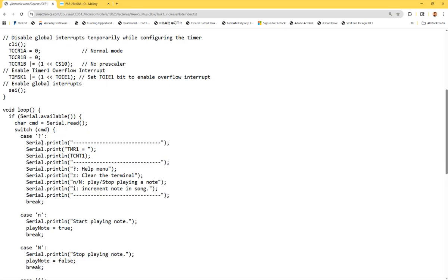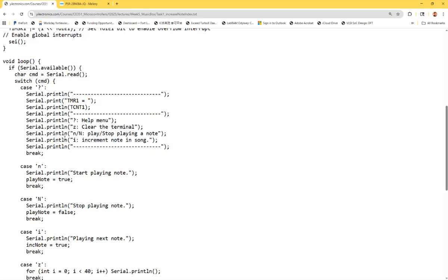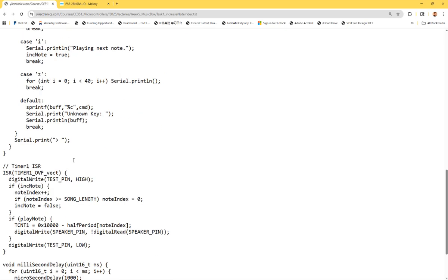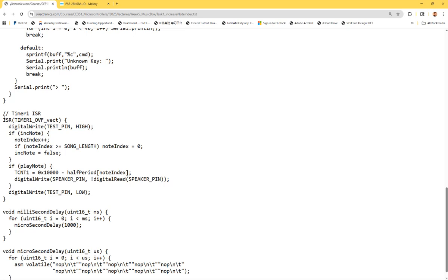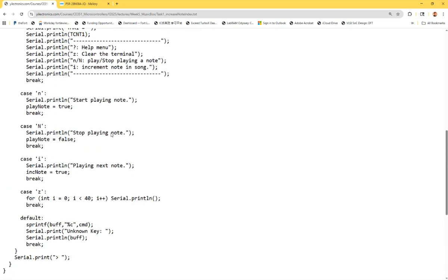Okay, so in order to make our microcontrollers more capable of handling multitasks, we want to add an interrupt service routine or ISR to it, which is able to interrupt based on the signals, right? So, for example, for this tutorial, we are using an overflow interrupt.